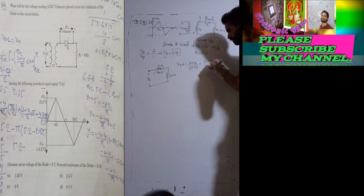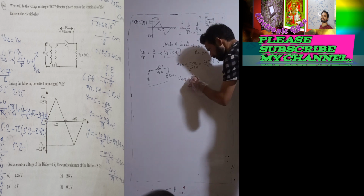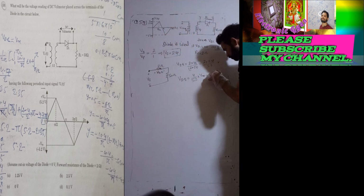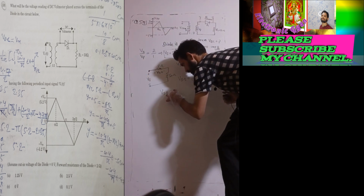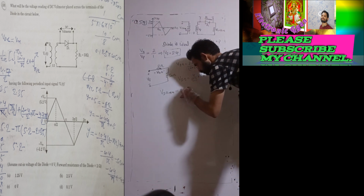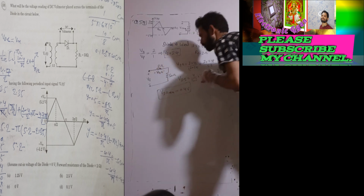So V2 ohm is 4 by 52 into Vm. What is Vm here? 5.2. So 4 into 5.2 divided by 52. Therefore the V2 ohm maximum that we get, 52 and 5.2 get cancelled, this is 0.1, which is nothing but 0.4 volt.